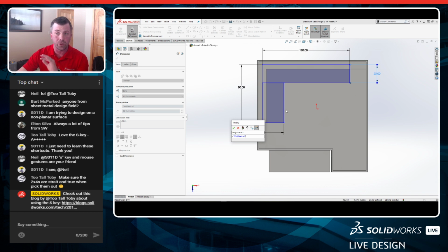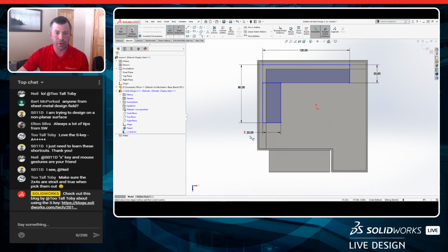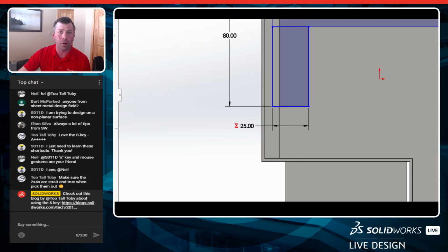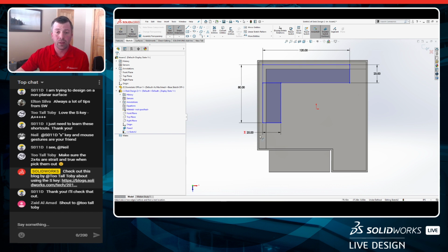So that's going to be equal to, the naming convention here is it's the 3rd dimension I added in the 2nd sketch I created. So if you ever wonder what that D3@Sketch2 is, it's the third dimension I added in the second sketch that I've created. So go ahead and click OK. You'll get a nice little Sigma symbol. And really what that's highlighting is that we are driving that from an equation. So from the user's perspective, I can see, all right, this is intelligent. It's being pushed off of another equation or an equation itself, and you can take a look at that.